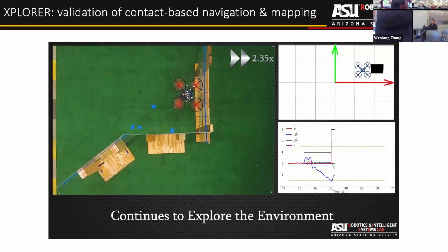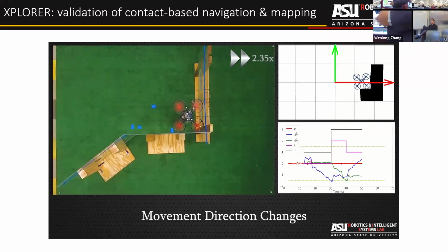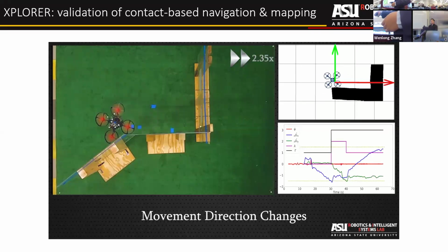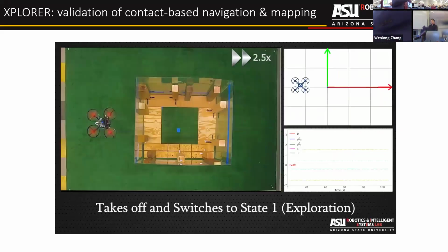So we know, okay, the drone is yawing here, and then at that time the wrench estimation is in this direction, so I command the drone to go here, right? So originally the wrench estimation is in this direction, so it goes perpendicular, and now it goes in again perpendicular direction. Here's a yaw, and then the finish, and that's the map it generates, right? So similarly, you can do the same thing for another shape.